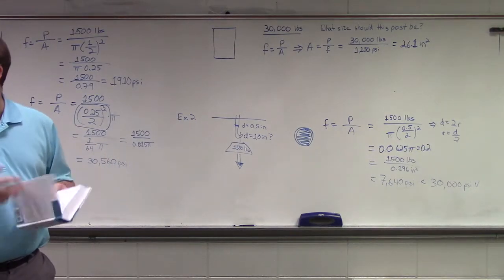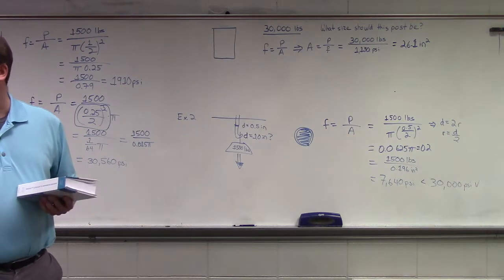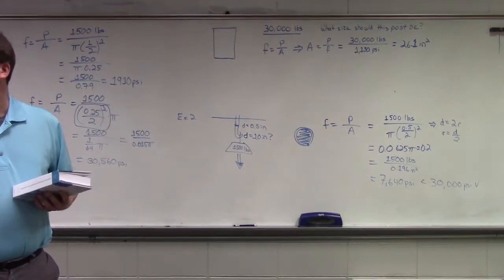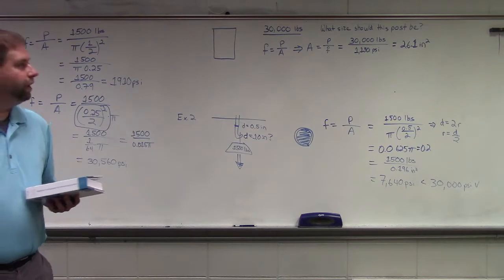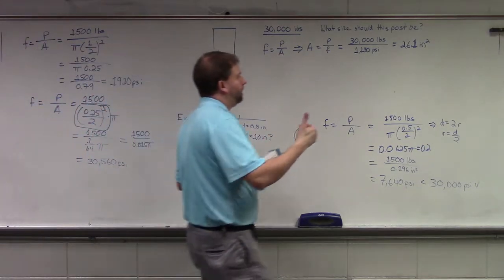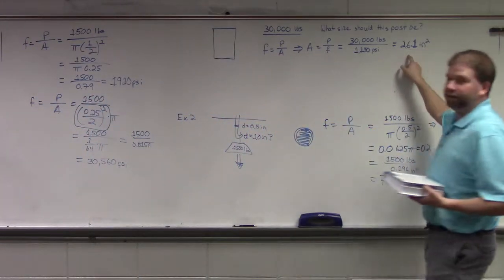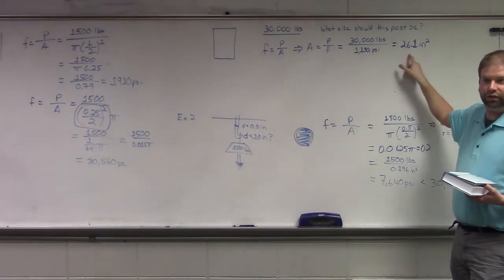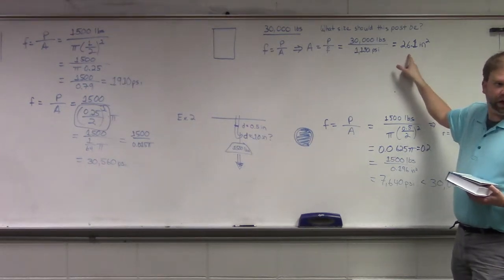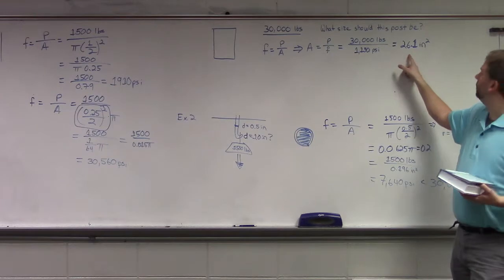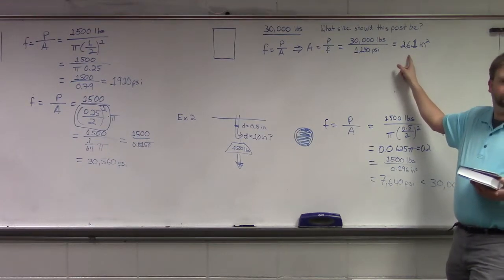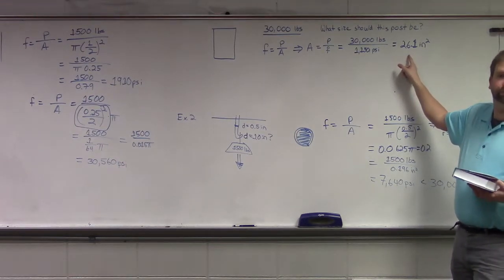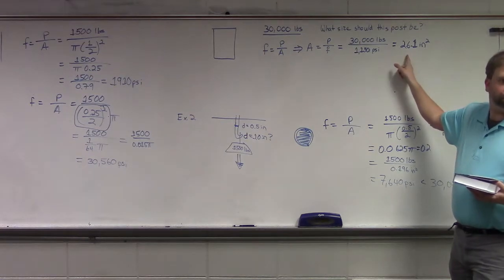What do we need to remember about lumber? Is that our actual dimension? No, now we're talking about a nominal dimension. If we're dealing with a 4x4 square post, even if it is truly 4 inches square, is that sufficient area? It's not going to be sufficient. What about our 5-inch? We're still going to be shy. What about our 6-inch? Now we're talking.